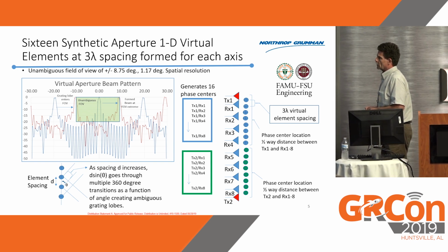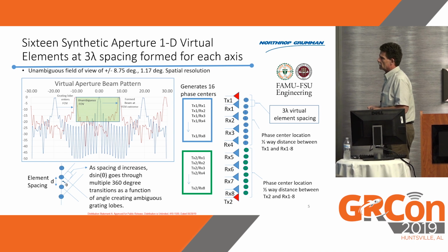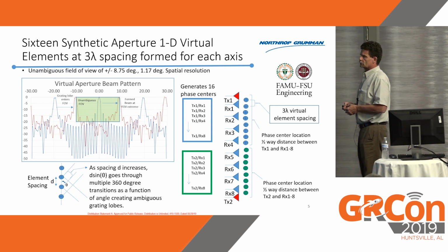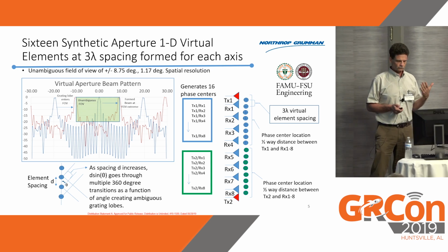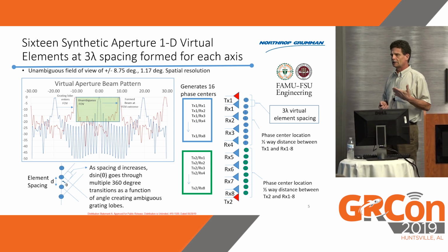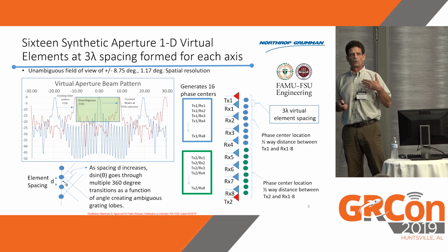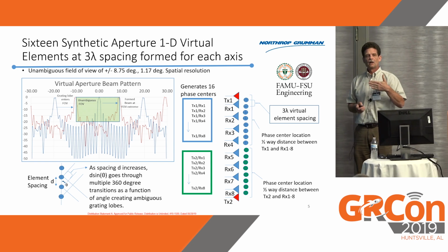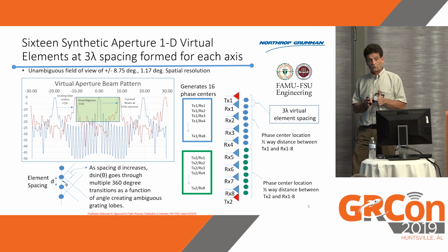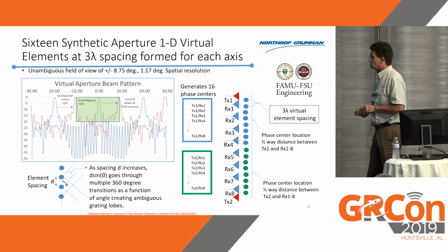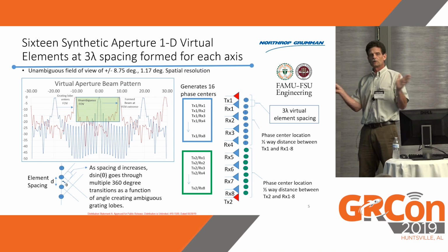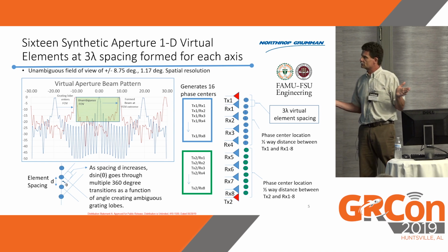One of the key concepts to understand is that when you do beamforming spatially in azimuth and elevation, it's really dictated by how close you can get your elements. In our case, we couldn't get the elements at lambda over 2. In the same way that in the time domain we have to sample frequently enough so you don't get aliasing that corrupts your rendered signal in the digital domain, in the spatial domain, when you sample a scene elementally, you have to have the elements close enough together, or you get grating lobes, which distorts your real space.